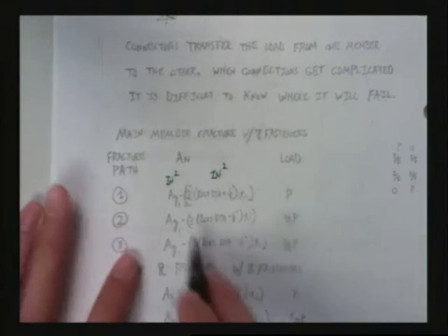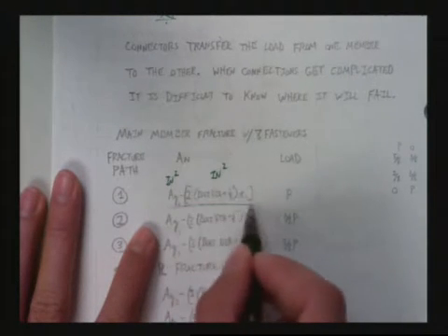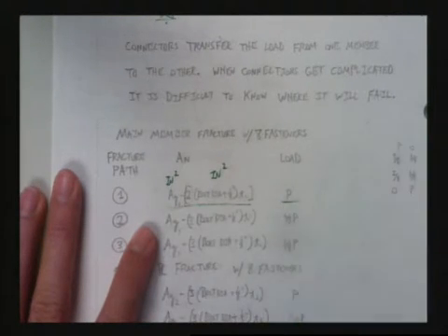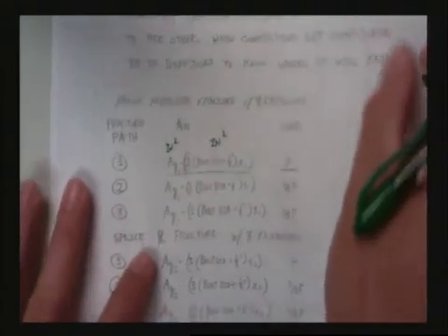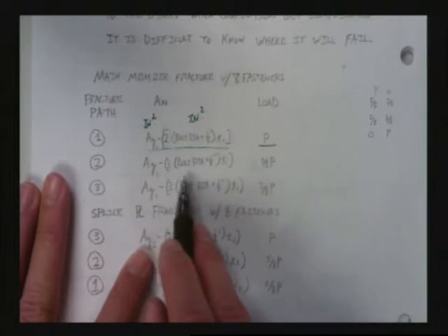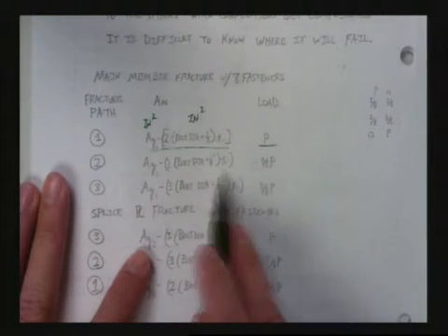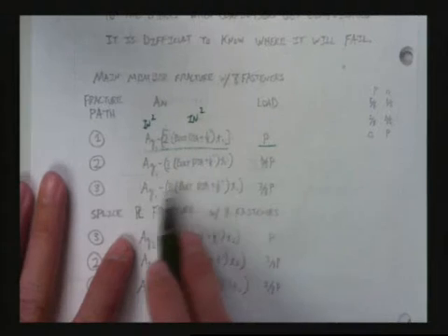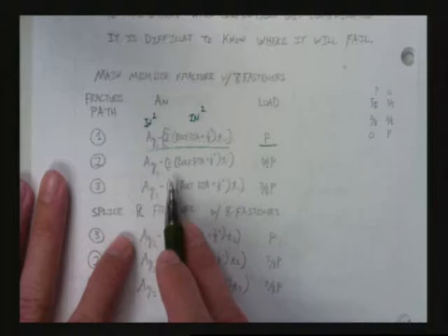Okay. So you would find this would be your net area, and you would compare it against the load P. Yes. Then you're not done, are you? No. Then you do line 2. Line 2, you do the same thing. You'd say area gross minus 3 bolts. Why do we use 3? Because there are 3 bolts, right? And you'd see 6/8. So we don't know. We'd have to plug in. We'd have to determine for ourselves.